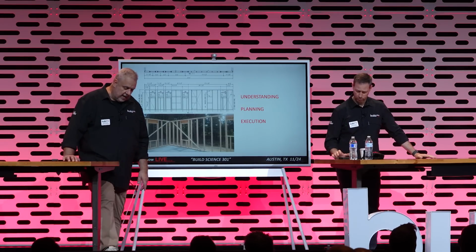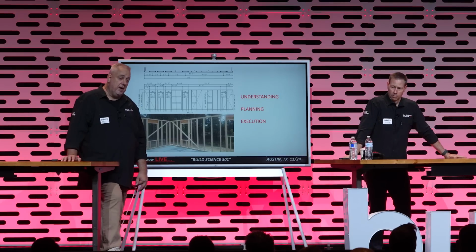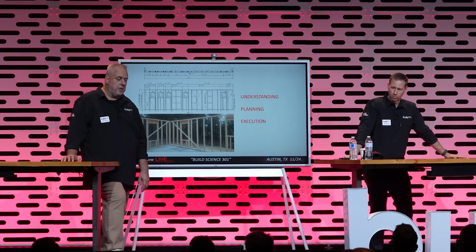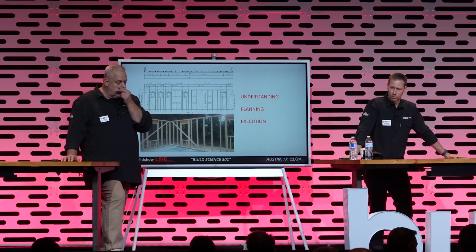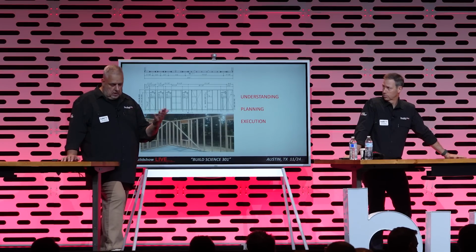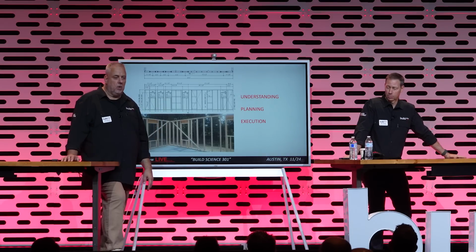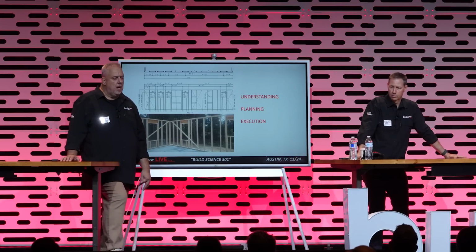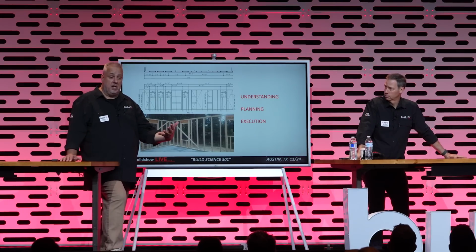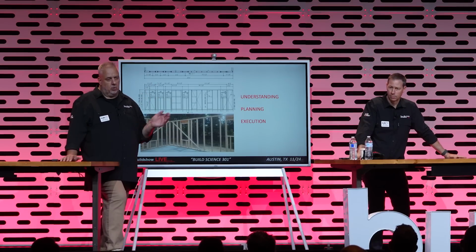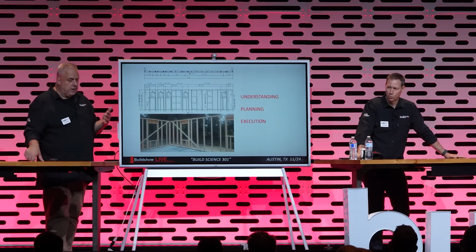So when I worked at Building Science Corporation, a lot of our time we spent drawing elevations and trying to convince people into advanced framing and 2-stud corners. And remember, given my age, this is late 90s where I'm doing these drawings for the Builder's Guide and stuff. But it really helped me as a young architect. You can imagine it put me kind of in framing mode where I had to step out of the corner 2 feet and account for the wall that comes into that, perpendicular on the other side. But it helped me understand things. It also helps me understand when you look at that drawing, there's basically 3 components to the wall.